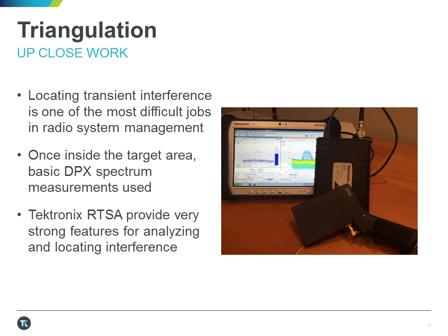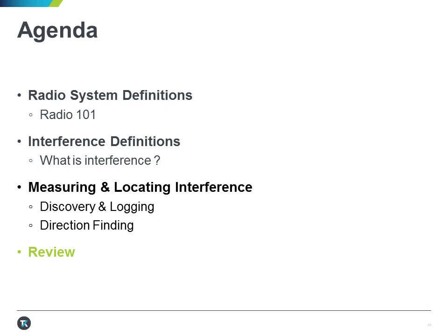Once we're inside the area of uncertainty, or we think we may be close to the target source of interference, it's important that we use non-active antennas in our work. As you get closer to the emitter, depending on the power of the emitter, active antennas can be easily overloaded, and this will cause a great amount of trouble as we're trying to determine the source of energy.